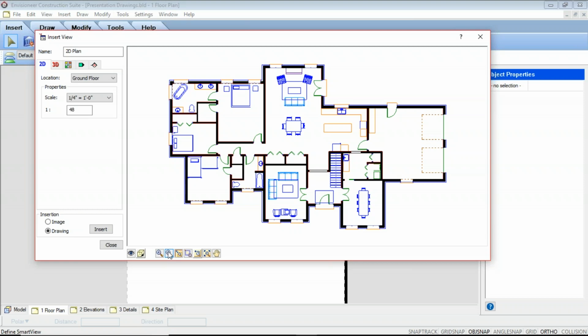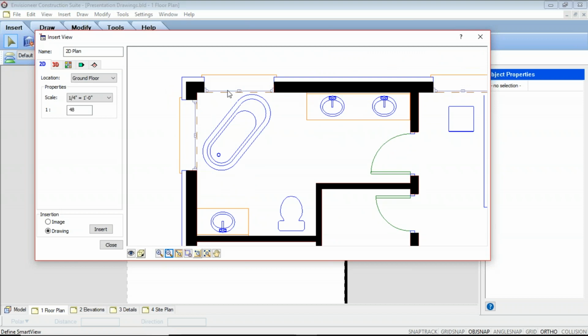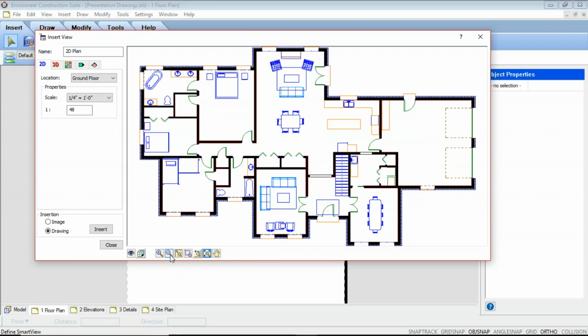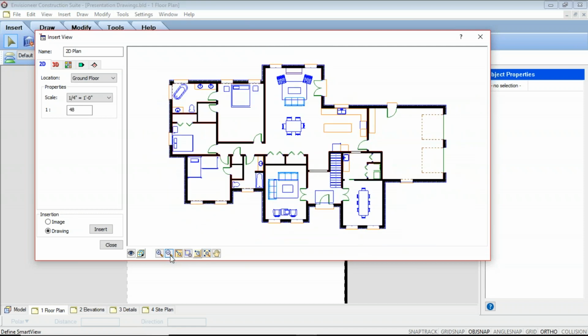While I'm in this view, I also want to turn on the pattern mode. So this will actually show me any kind of hatch pattern that's associated to any of my elements. So if I zoom in real quick over here, I can see that I have my walls. And if I go down here and I select display mode, I can go down and select patterned. And it's now going to show me the hatch patterns of that wall. So I can see that that's now a brick wall, and I can see the solid fill of my walls as well. So the core is being solid fill. Again, just zoom extents, zoom out with a couple of clicks of the zoom out button, and we can see the actual shape of our design.